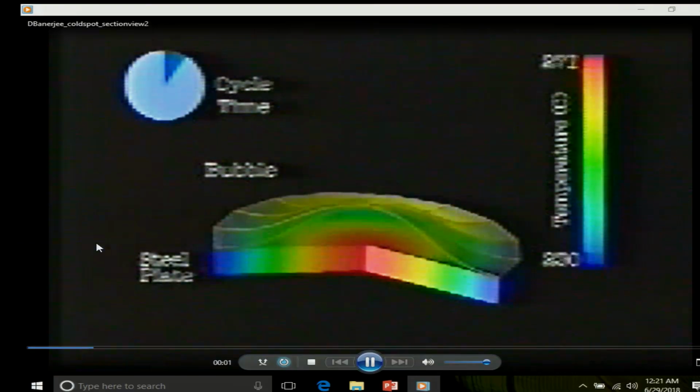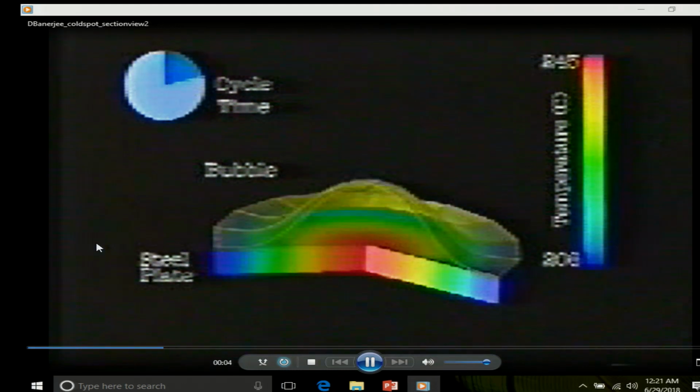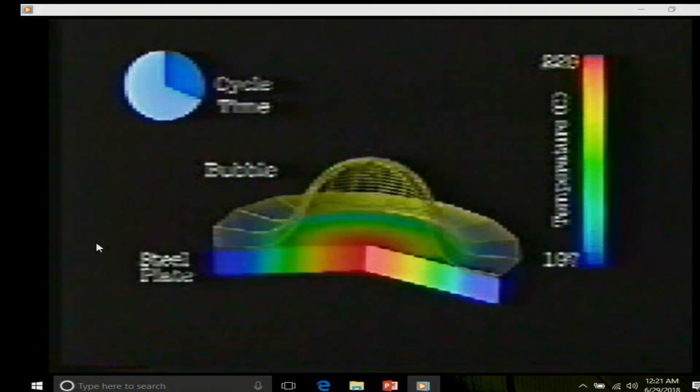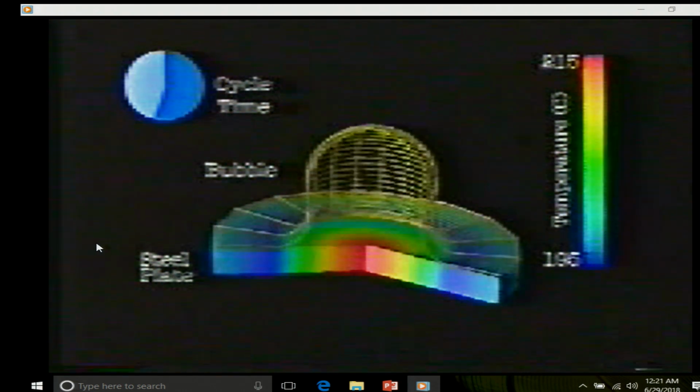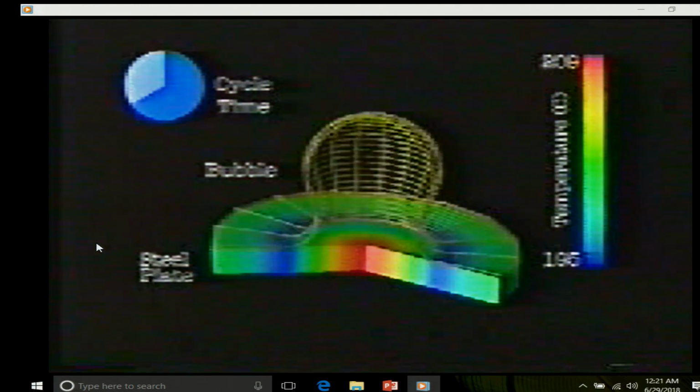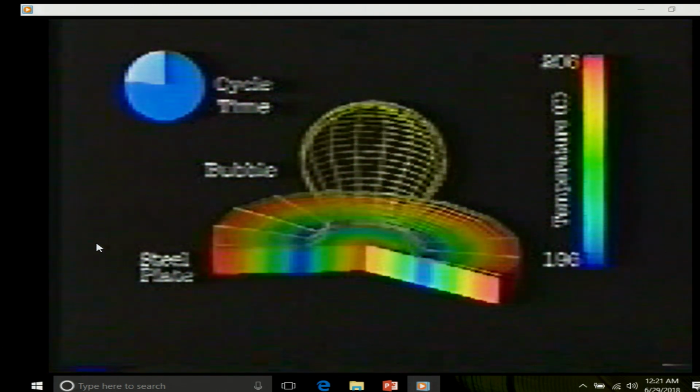And so, like a rocket nozzle, it is dumping a vapor jet on that surface, and in the process it is cooling the surface, and the liquid is getting vaporized and ejected off like a rocket. That is how it is all working. The location at which I have a peak in the heat transfer, particularly at the point of minimum vapor film thickness, or wherever this solid-liquid-vapor interface happens, is where the temperature is lower, and it is plotted in blue.